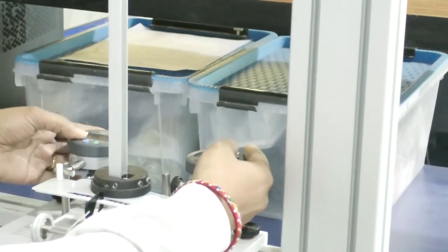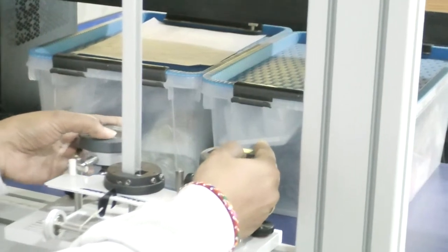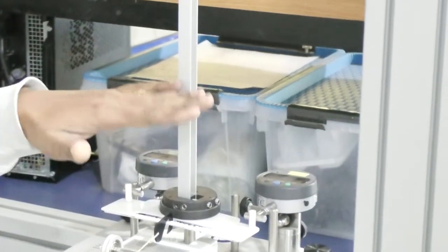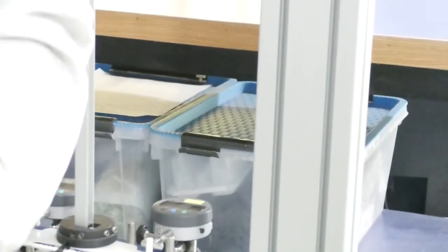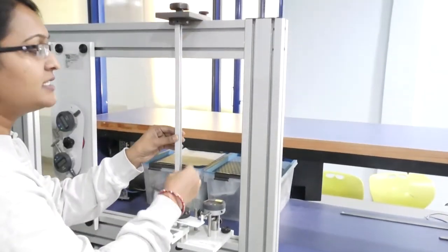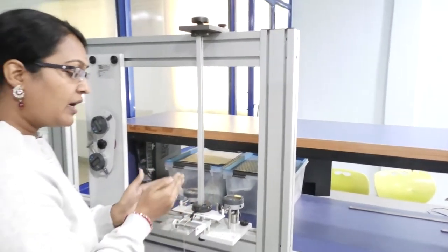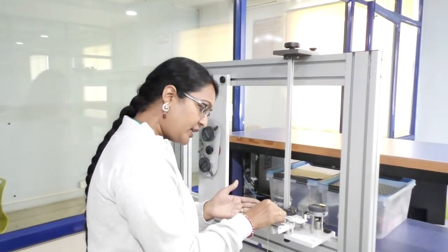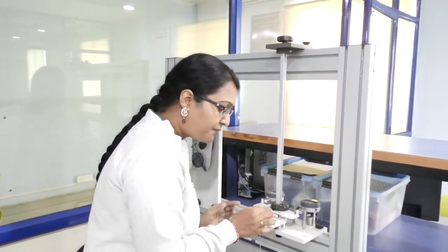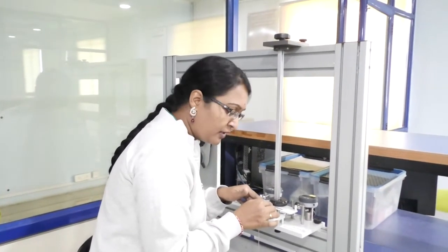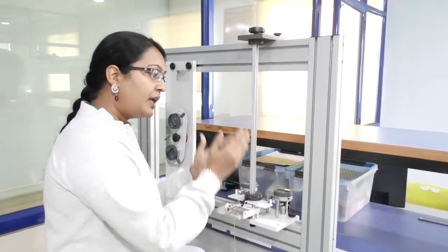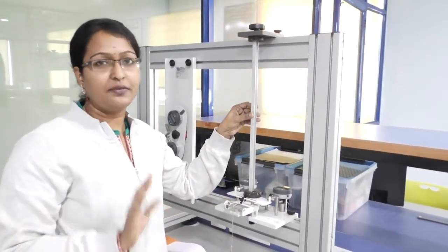Now set these two dial gauge indicators, which are used for measuring deflection, to the origin first. When both are set to the origin, it is in a pure bending position, where the shear center is applied. Now we move our hanger from this origin to other points, where each point is 5 mm. So when we go positive 5 mm and negative 5 mm, we are going to find where we get pure bending. That is what we are going to calculate.